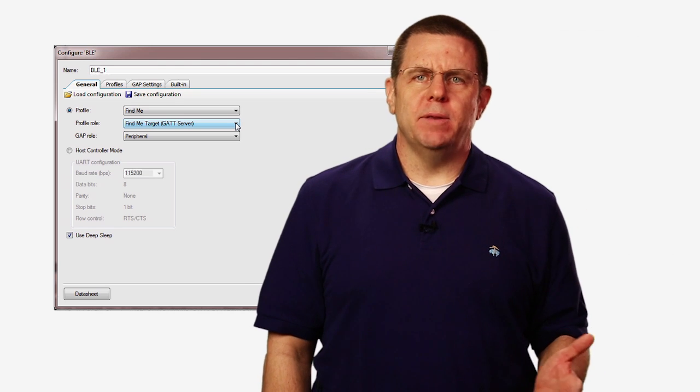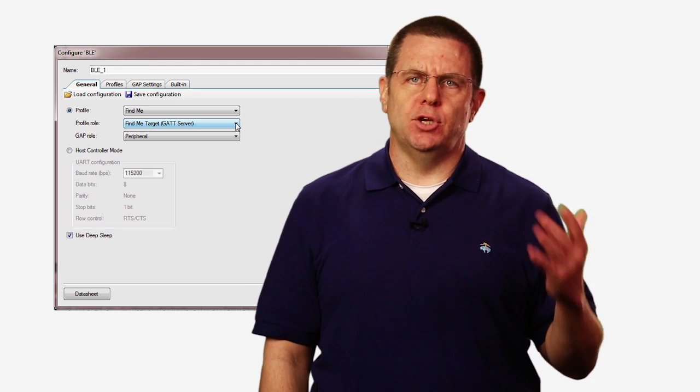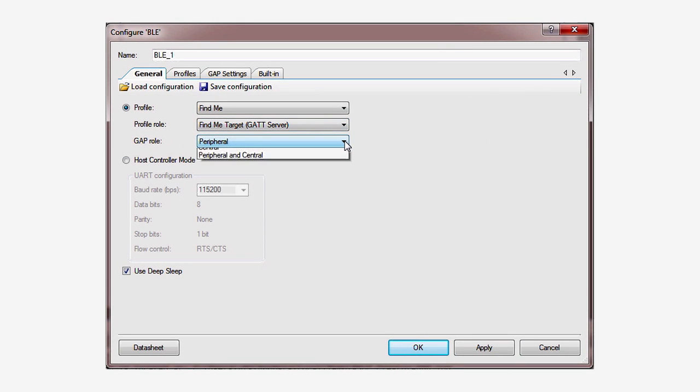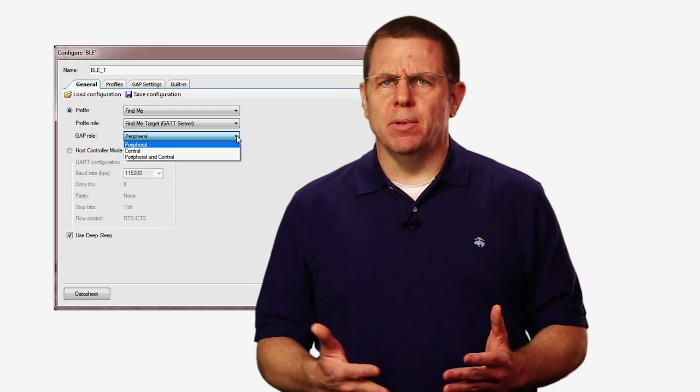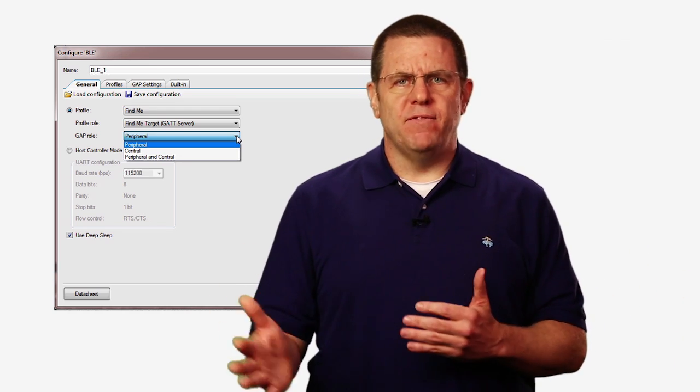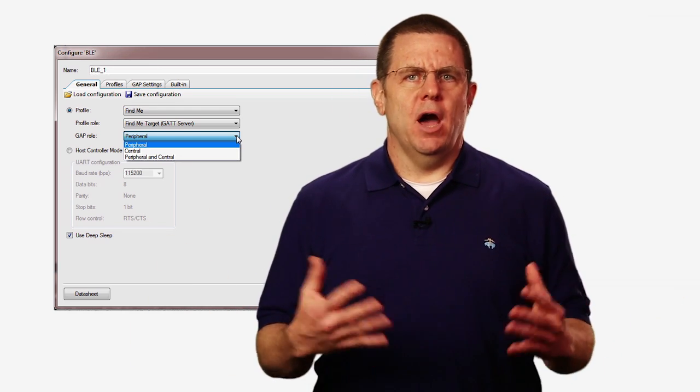The connection between BLE devices is established using GAP. The two main roles in GAP are the GAP central, which is most often played by a cell phone, and the GAP peripheral, which is most often the thing you're building. Our device is capable of serving in both of these roles and in fact switching between them. However, that's pretty complicated and is outside of the scope of these Getting Started lessons.